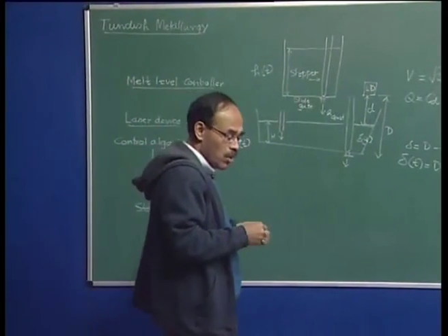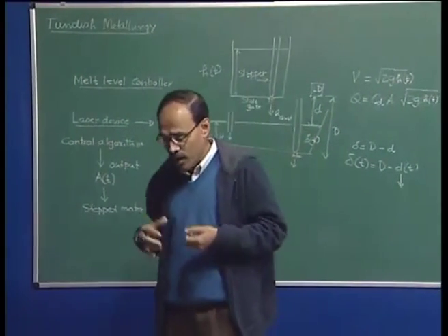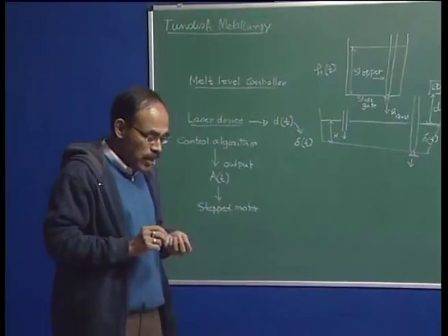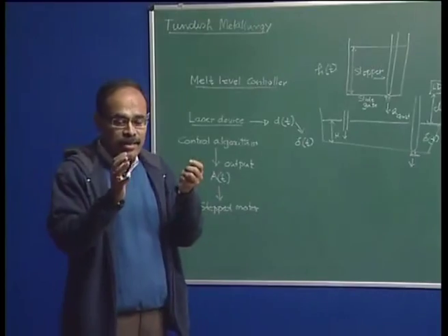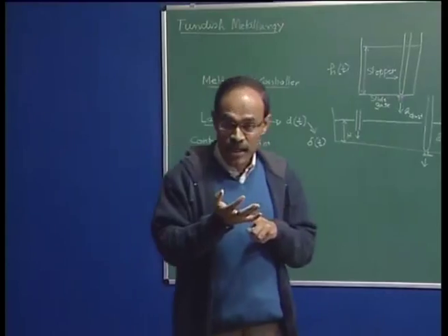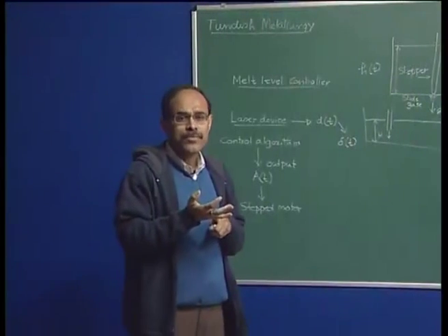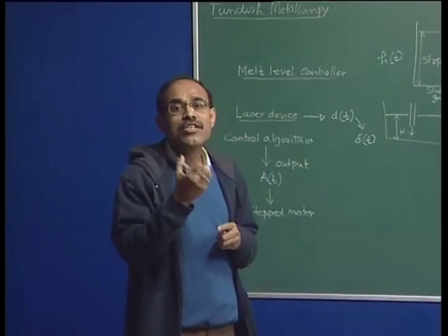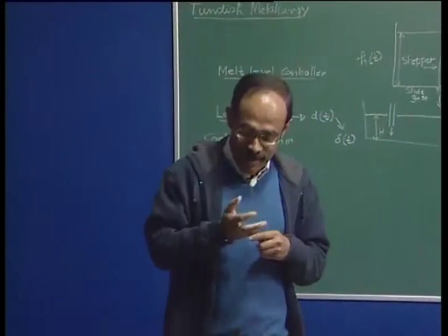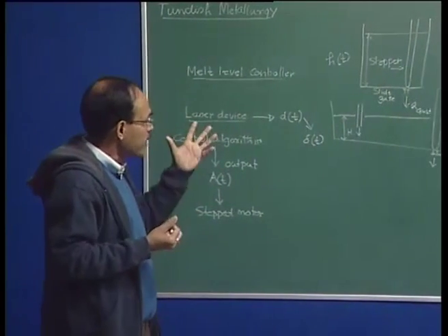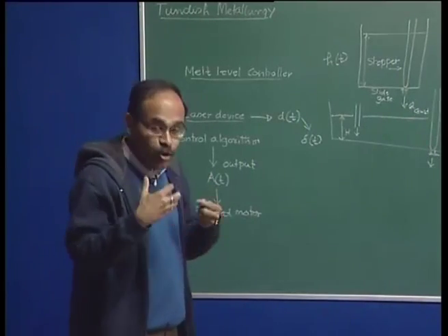So, we come to the conclusion of our discussion on ladle and tundish metallurgy, and quickly I would now like to summarize what we have done in ladle and tundish metallurgy. Basically, the ladle and tundish metallurgy are applied in order to profoundly influence the quality of steel, and also we have seen the productivity of steel as well. Now, when you talk of quality of steel, basically it is in terms of achieving the right composition, the correct temperature, and the correct cleanliness. And these are the main motto of the secondary steel making processes, and it starts following the tapping operation.